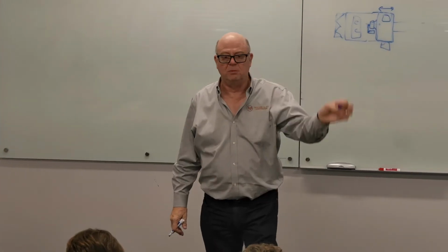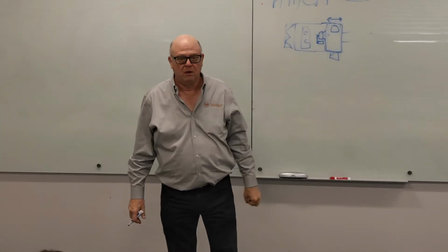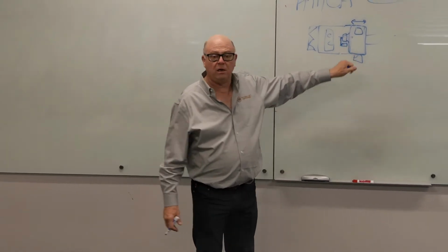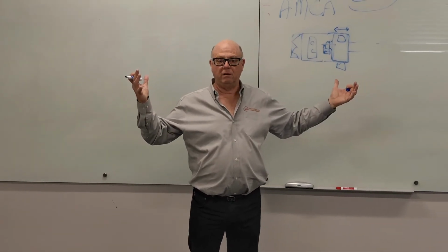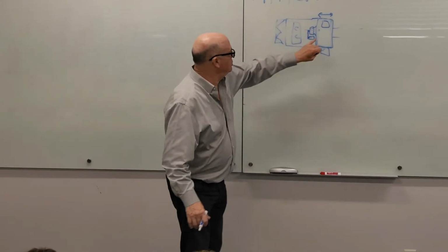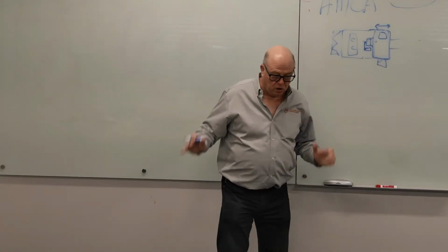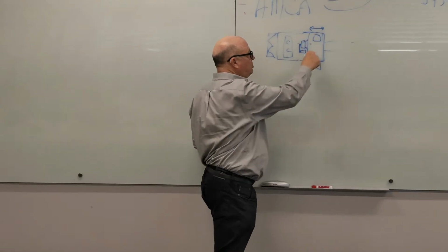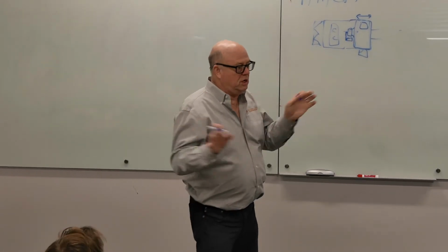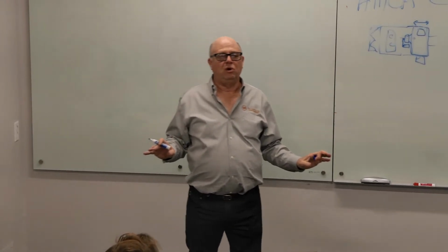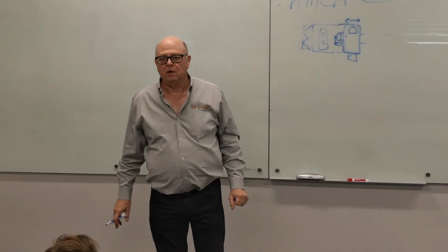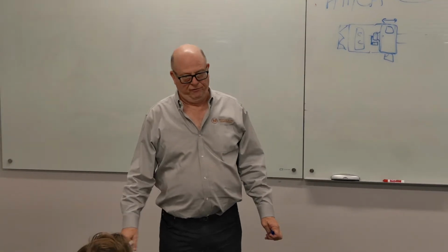You don't have to worry about system effect. You don't have to worry about any of that stuff. You paid for it right here. And the fan curve you get for this air handler, it's built around that. It's not built around 10 straight duct diameters. The manufacturer of this air handler will give you a curve that's built around the idea that you are pressurizing a plenum with it. And that's what the curve's based on. So you can be a really bad engineer, and if you do this, you're pretty much bulletproof.